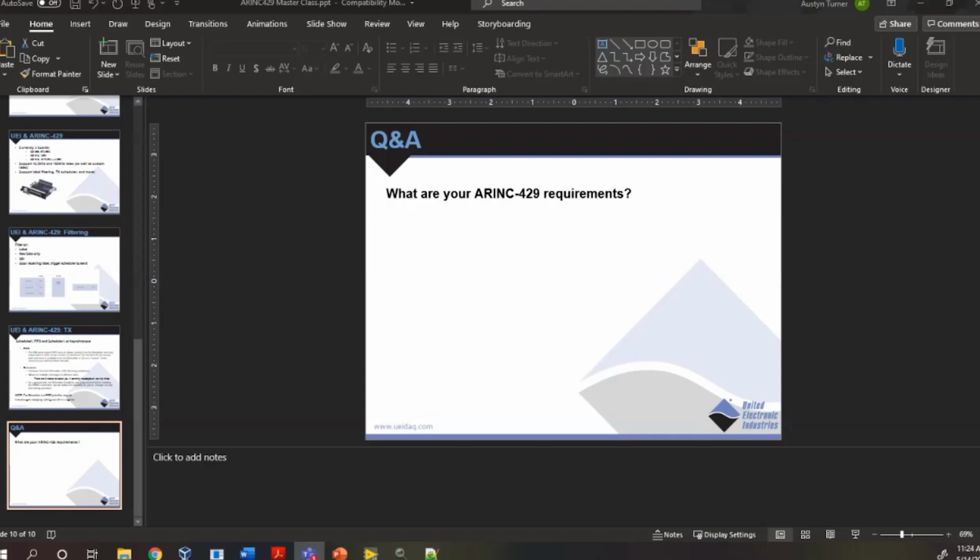Can you please elaborate on the non-tethered mode of operation from a programming perspective? Yes, so we have two main modes of operation. One we call tethered or Powered DNA. That's where your application runs on a host PC, and your application could be written in C, C++, LabVIEW, MATLAB. I know I'm missing a few of those, but there are a lot of languages that we support. So again, your application is running on your host PC, and it's communicating over Ethernet to one of our chassis.